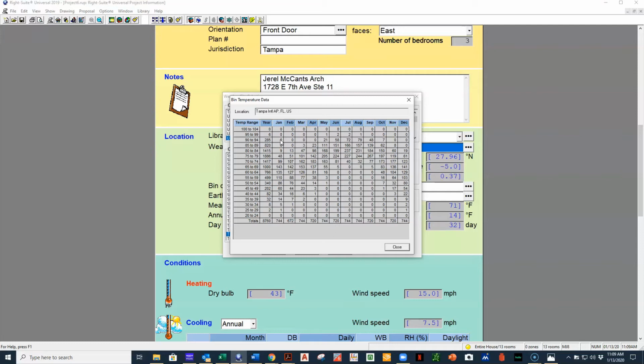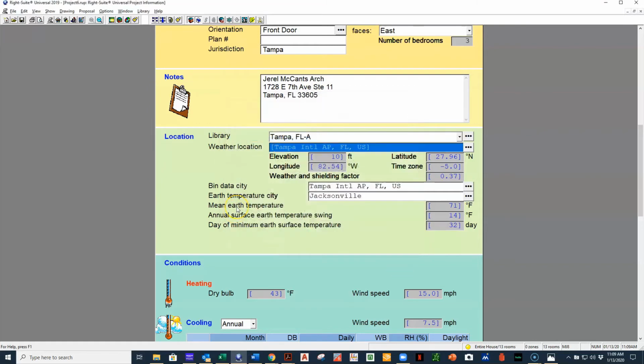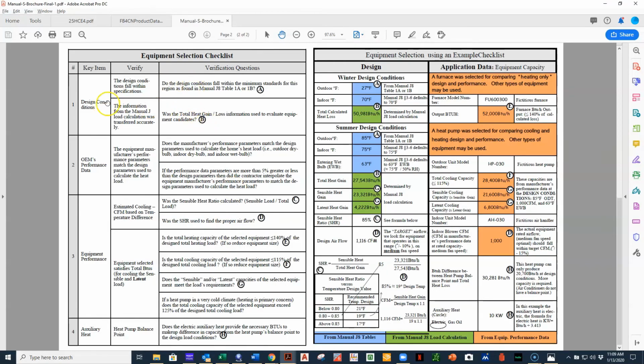And that'd be something that you can experiment with in your projects by modifying the outdoor temperature slightly to see how many degrees you have to go above the outside temperature before it affects the cooling load. So very important that you know that. So that's what it's talking about when it goes here for your tables. But you want to read through this and you want to understand, and then it references over here to help you get an idea of what each of these letters are referring to.